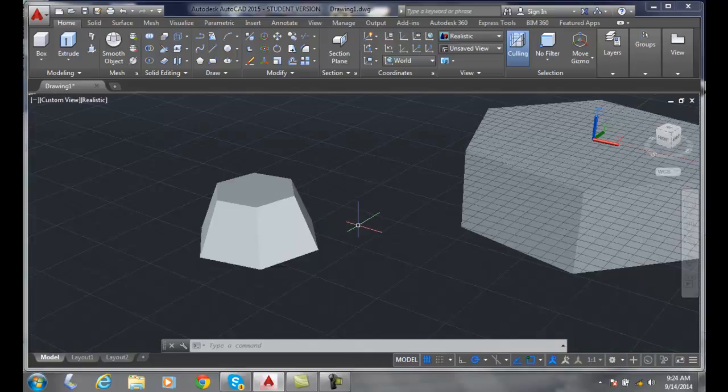negative 90 degrees to a positive 90 degrees. So it can be a little bit of taper, a lot of taper. Typically we have these in molds. If you think of a cake mold or something, we have about a 5 to 10 degree taper to get the parts out of the mold.